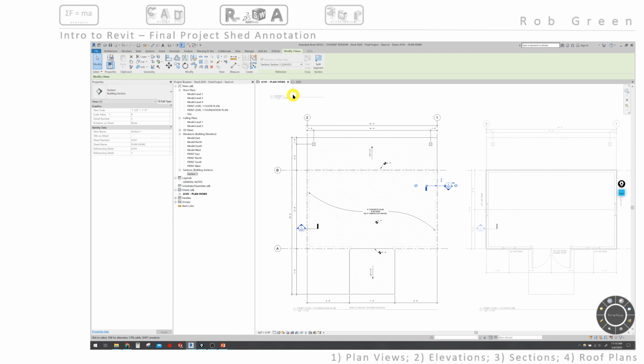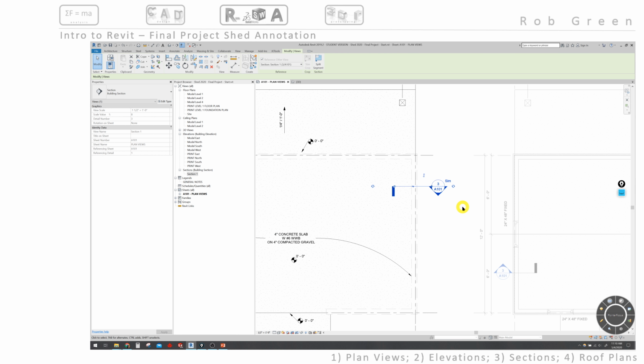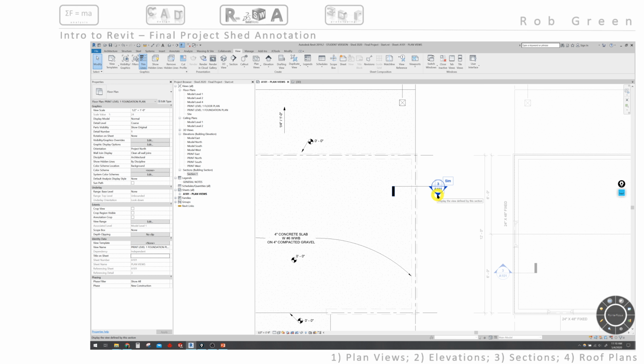And that's what the actual section view shows. So one section is pointed up, the opposite is pointed down, and notice Revit gives us this little SIM, meaning it's similar. So it highlights to me as a creator that this callout isn't actually generating a view, it's referring to another view. So I'm going to leave that here.